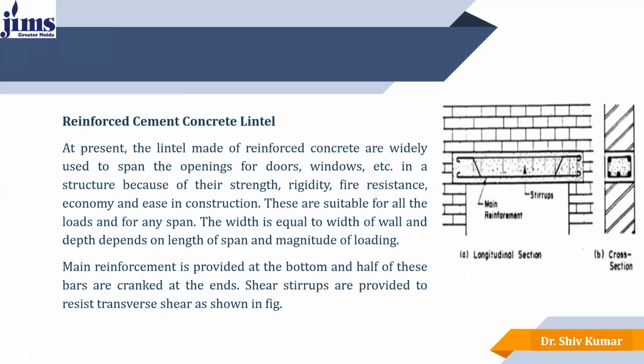The next is the RCC lintel. At present, lintels made of RCC are widely used for the span and opening of doors and windows in a structure because of its strength, rigidity, fire resistance, economy, and ease of construction. These are one of the most suitable lintels which are provided in the buildings.